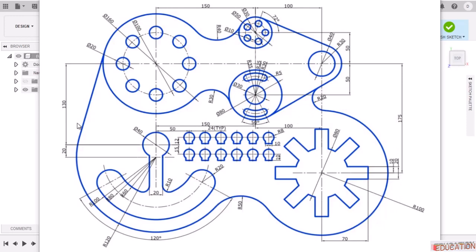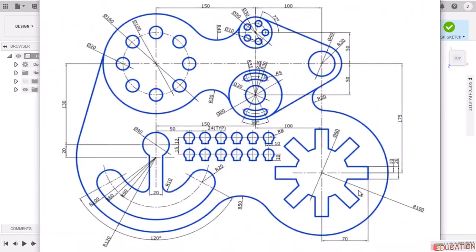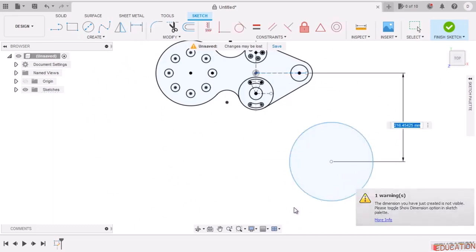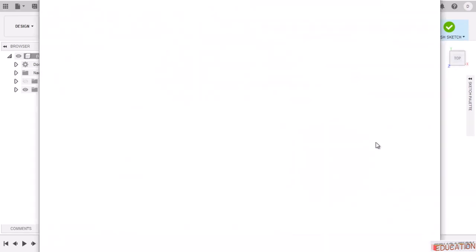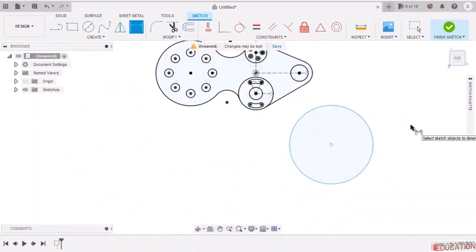and then we will go for creating this circle and constrain it. This we had created in the last lecture. Now we'll create a circle here, and if you see the dimensions from this x-axis that we have created in the earlier lecture, the dimension of this center is 175. Let us create it step by step. So from this axis to this point, this value is 175. Let us give that 175, enter.